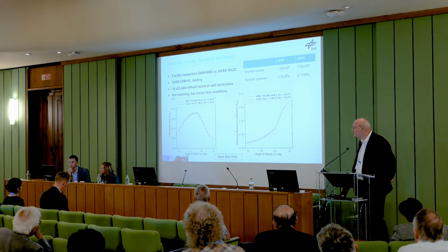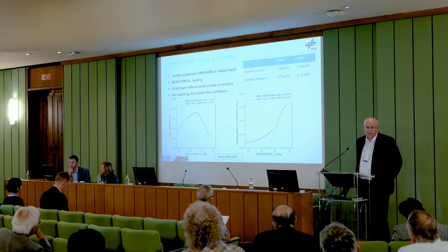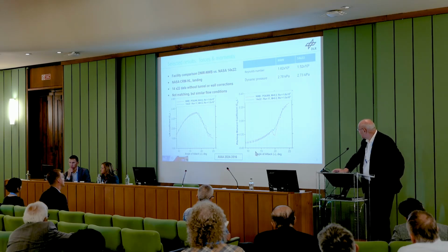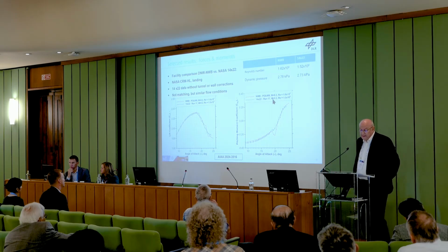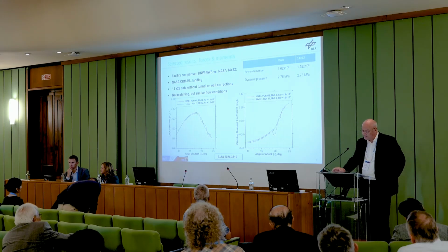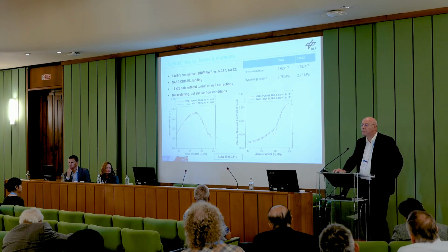I start with forces and moments. And the first has already been shown by Melissa. That is a comparison between the D&W polar, NASA configuration, landing, reference conditions. Melissa mentioned that Reynolds number has been close but not really matching. And you can see that the data agree with each other, which is a good sign, I would say, and are fairly close together. Even the pitching moment is in close proximity. So that was a reason to go on with these tests and be sure that the basic model setup in the tunnel should be okay.